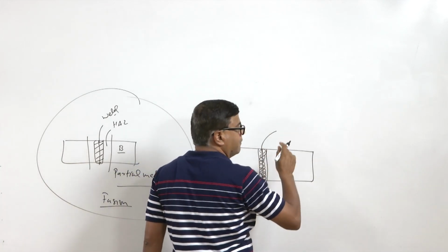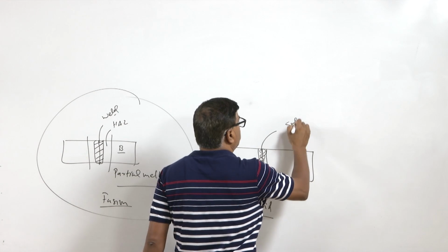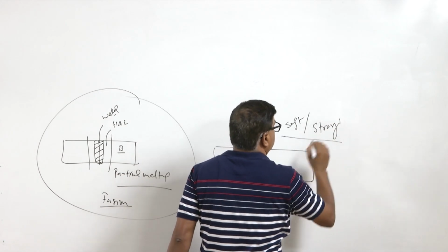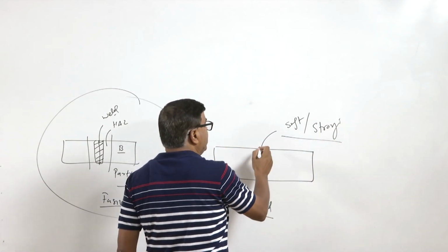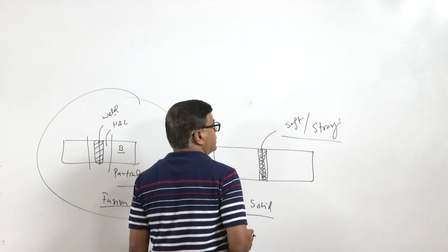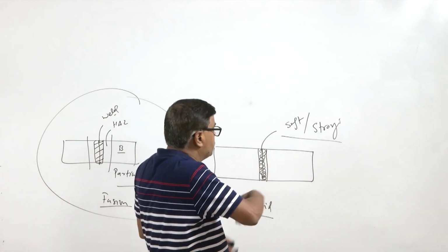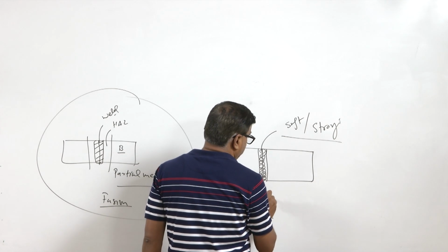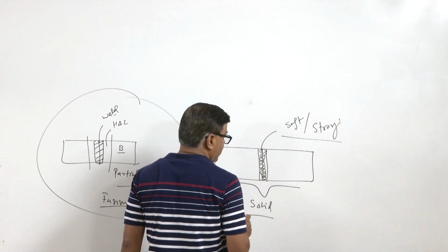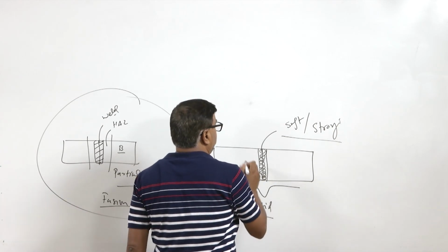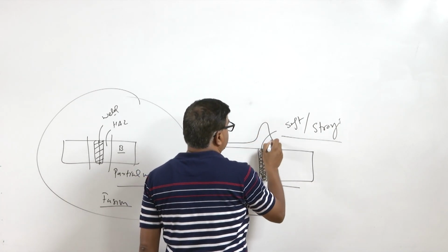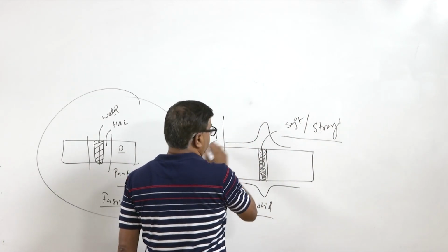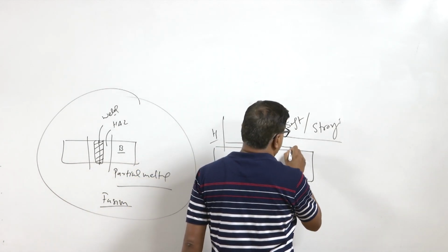Depending upon the strengthening mechanism of the metal, this zone may be soft or strong and hard. Those metals which are work hardenable will show a lot of increase in strength and hardness, as compared to the precipitation hardenable alloys, which get softened because of the deformation. The softening can be seen as a dip in hardness in the heat affected zone and the weld nugget zone, while when hardening takes place, the weld nugget will be stronger. This is the variation in hardness as a function of distance from the base metal across the weld joint.